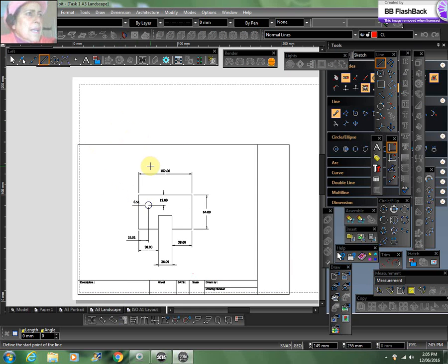you will see a border of this drawing up there. You have to hold the handles and drag it and bring it to these four corners of your paper space. So from this corner to this corner to this corner to this corner is the paper space that you adjusted to that level. That is how you bring the view of that object to this paper space for printing.